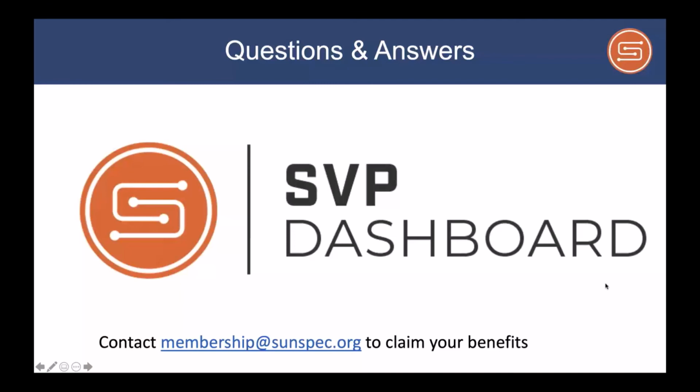And I will answer it thusly. Whether it's a client, server, or an aggregator in IEEE 2030.5, SunSpec Modbus has a semantically identical representation of the information that is transferred to support these smart DERs. So again, it's an important consideration just for the fidelity of your signal. The more common application of the gateways, I think, would be a local client running close to the DER system, interfacing with Modbus. But you are correct, Jason, that the other scenario is equally applicable.